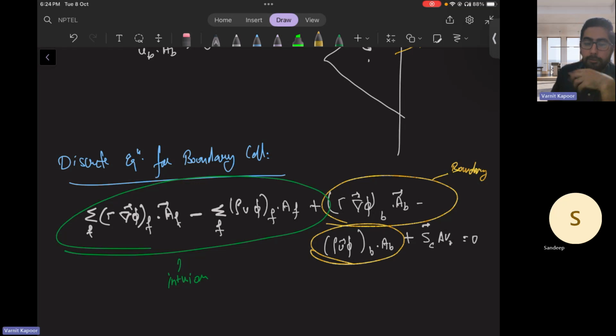So again, for the outflow boundary, we call the particular cell one that has faces in the outflow. The dot product is positive in this scenario. The outflow boundary is a kind of boundary where what happens inside dictates what is leaving through the outflow, depending on the flow rates. So we do not know yet what needs to be specified, and we cannot specify anything as of now.